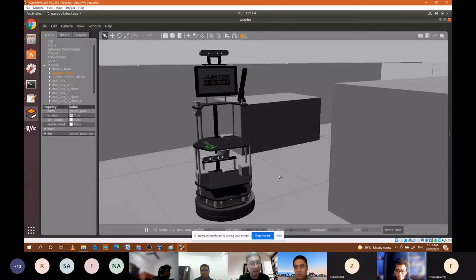Okay? And also, during your navigation, you might want to detect some objects on the ground. And radar can't actually give you any information about what object that is. You can only find obstacles, but when you want to recognize a certain object, for example when you move your robot around and there are obstacles on the ground, the only way is to do object recognition using the bottom camera. Using radar, I think it's very, very hard to recognize what the object is. Almost not possible, because you only have a 2D scan and you don't know the shape, you don't have the color, you have no way to know what it is.